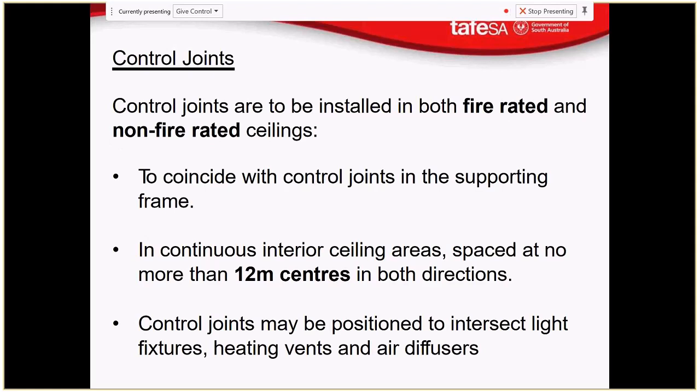Then we will have some adhesive and tape placed on that joint, and we'll get a slight sort of cupping happening in there, which is a good thing. Over top of that, our flushing compound is troweled on with a nice wide handheld trowel, and then sanded. Then a really fine coat once again with flushing compound, sanded to give hopefully an imperceptible joint.